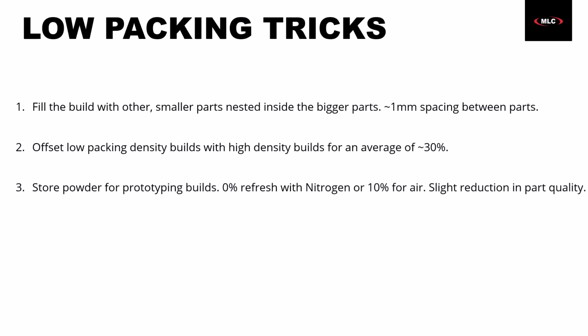The next thing you can do is store up a bunch of this used powder and then save it for a prototyping build. So with nitrogen, we've seen builds as low as 0% refresh, and in air, we've seen as low as 10% refresh, where you may have a slight reduction in your part quality and your physical properties, but you can still have a part in your hand for fit and function.